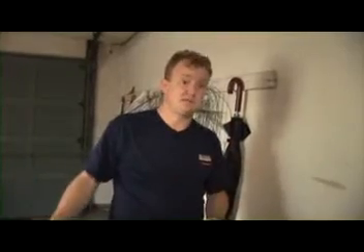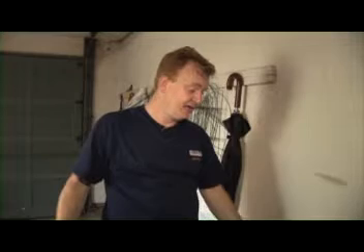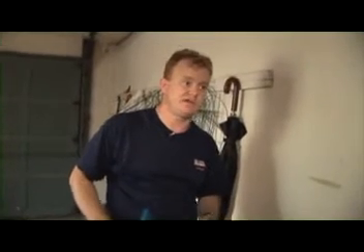1, unconditioned space gets very cold in the wintertime, so you're going to have warm air from the house finding its way into the garage, heat loss. And 2, if a car's running in here and there's carbon monoxide in the garage, it could potentially be pulled into the house. So that's another health and safety issue that we want to be aware of.